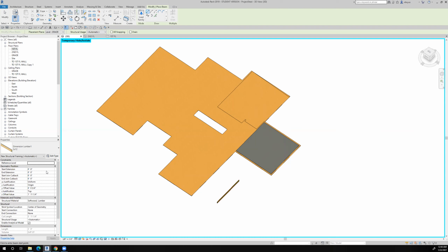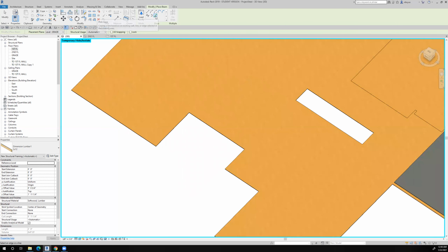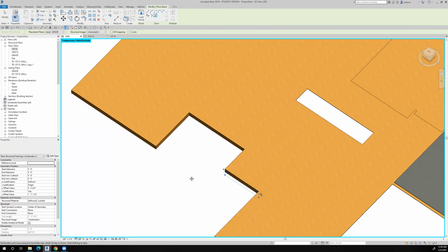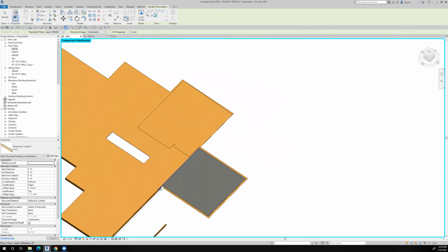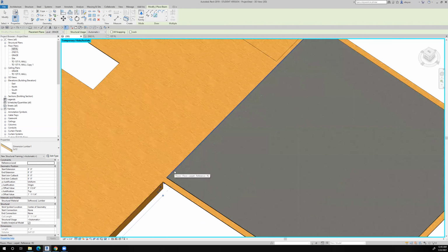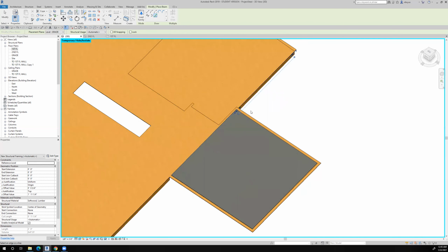And then if we took a look at it, we'd see that in this case, it picked the grade as my reference level. And so I need to be 1 foot 11 1/4 above the grade. And that might start to make a little more sense when I actually tell Revit in 3D that I want to put this member in, and I pick these edges right here. And Revit is very kind in putting in my rim joist very quickly, all the way around.